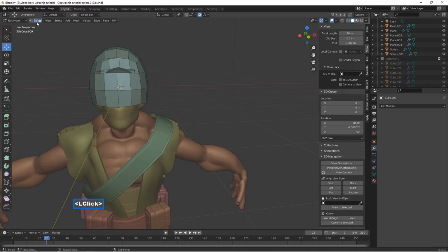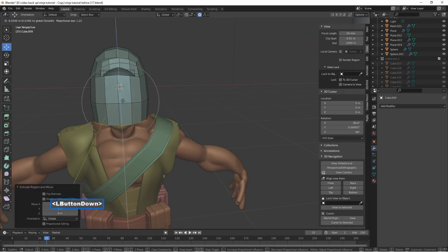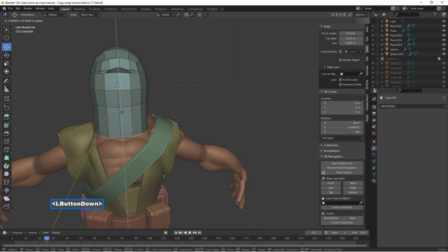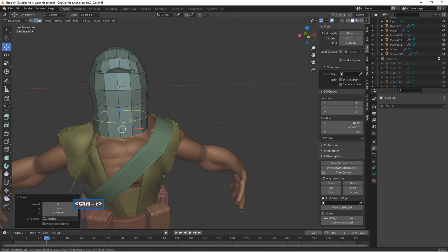Okay, we're going to go to edge select, hold Alt, select here. That selected the entire loop going all the way around. We're going to press E to extrude, right click. I'm going to press O to turn off the proportional editing tool. Push this down like this. I'm going to hold Control. One loop cut's good. So to make these, the extruding faces about equal with that.